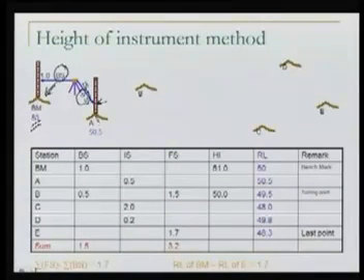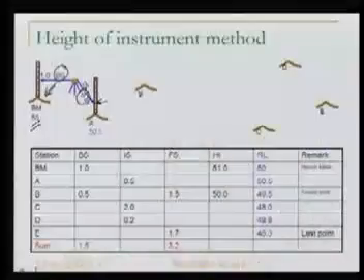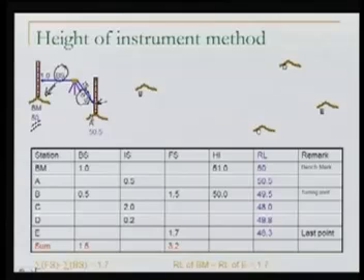We take the foresight to a point where we want to end one particular link of the loop. An intermediate sight is any intermediate point in between, where we don't want to shift our instrument. What I'm taking now is an intermediate sight. It's not a foresight yet because I'm not shifting my instrument after taking this sight. So this intermediate sight is 0.5.